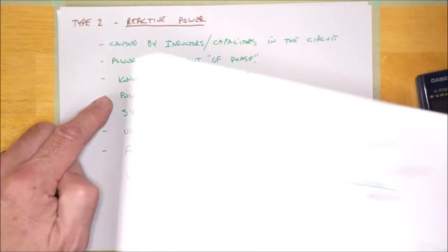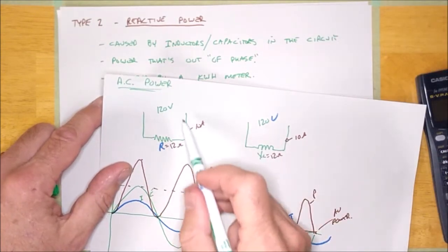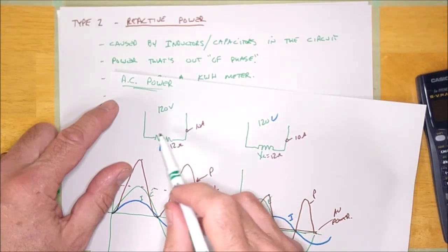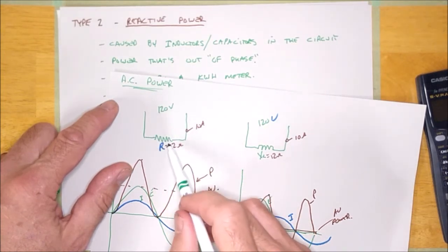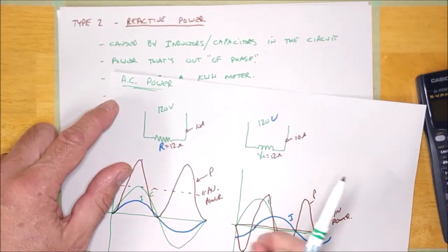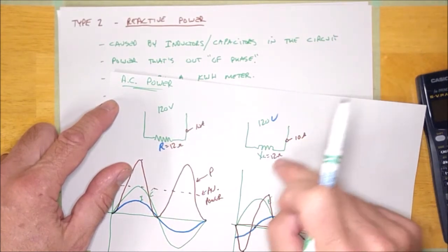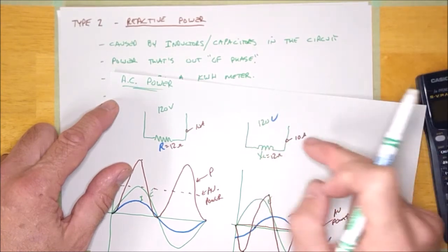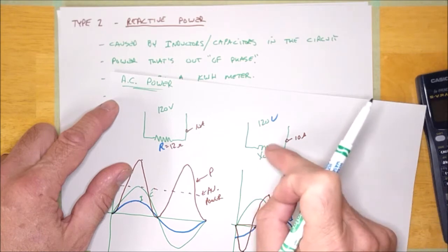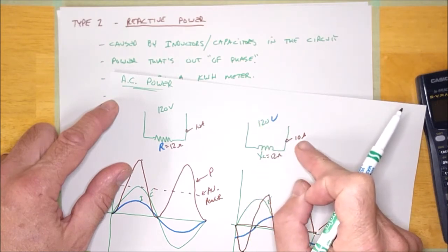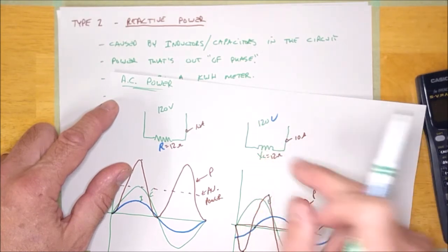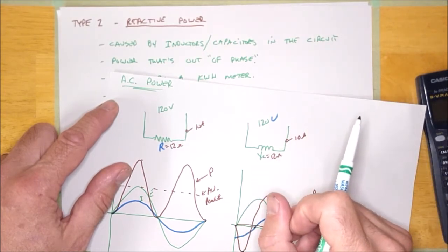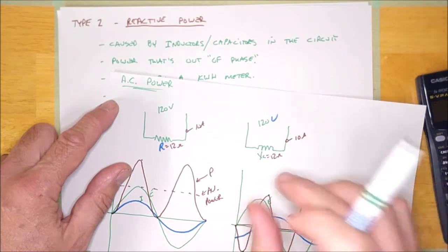What that means is, this circuit right here is all true power. That resistor is going to heat up. There's going to be 1200 watts, and you're going to feel it, okay? That's going to be a baseboard heater. This one here is also 1200, the voltage dropping across the inductor times the current through the inductor, but it's 1200 VARs, okay? But that inductor will not heat up. It'll just sit there and do nothing. You can't do any work with it.